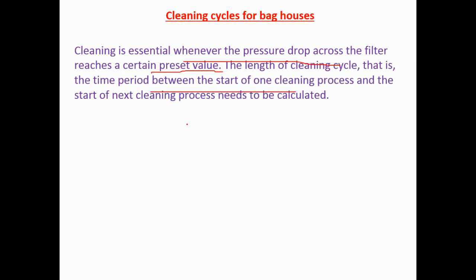These are the most important things for the bag filter, and bag filters are very efficient for dry dust collection. This is an important point: you can collect dust particles from less than 10 micron down to 0.02 micron.